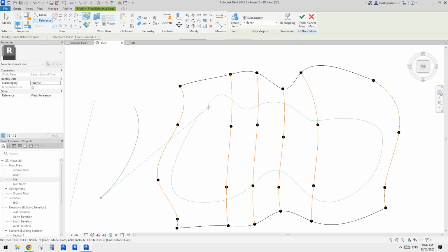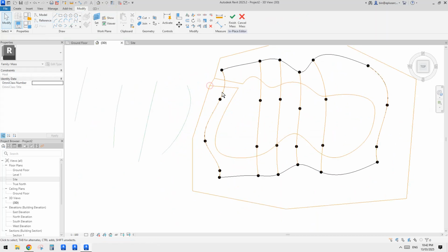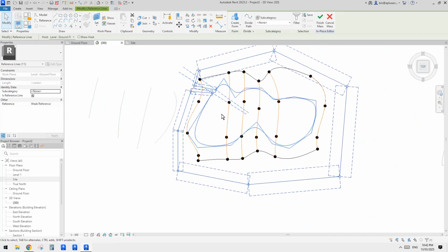and we can just draw something. Just go back to this, and then just do another shape, covering the whole massing. And with this one, you can just try to move your cursor here. So Revit, if you do this properly, Revit should automatically select, see this, and continue around this. So one closed loop. Okay, and then we can create a void from this.